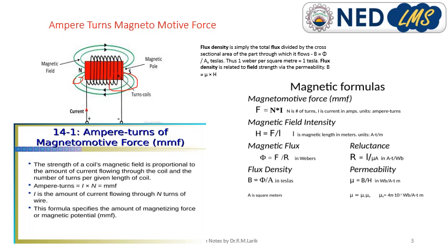But remember, when a step down transformer is used, the secondary side voltage is less, but the current is more. That's why the diameter of the conductor increases when fewer turns of coil are used. When more turns are used, the diameter of the conductor is smaller, that is, thinner wire.